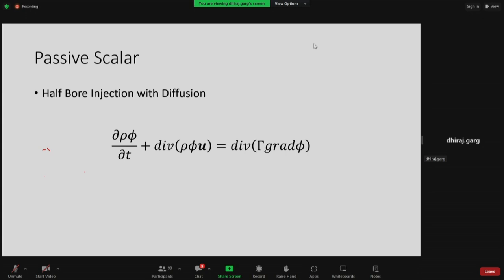The RTD analysis is always transient. It cannot be steady state because eventually it will cover the whole cross section throughout the system. So you won't see any variation. So RTD analysis, residence time distribution analysis, is always a transient analysis, and it continues till, as you have rightly figured out, it covers the whole thing, because beyond that you won't see any variation. So very good question. Thanks for bringing it up.